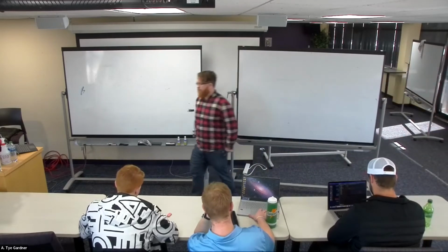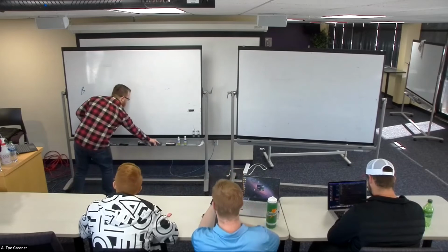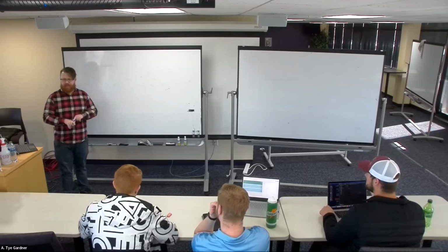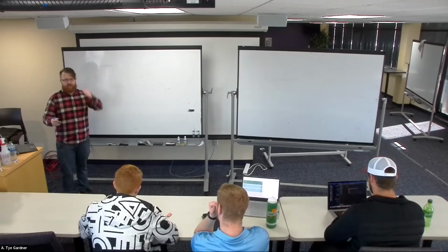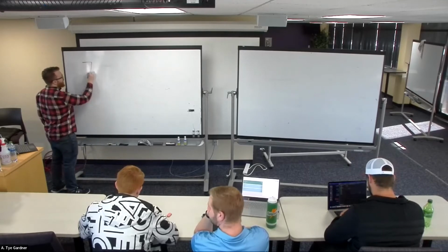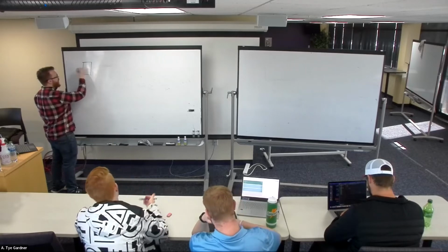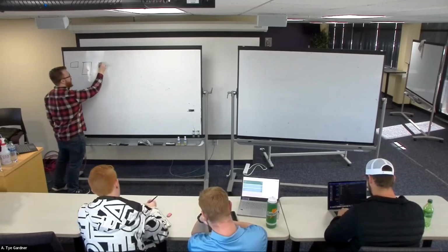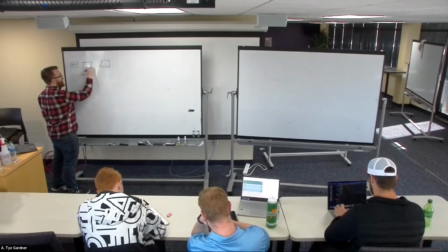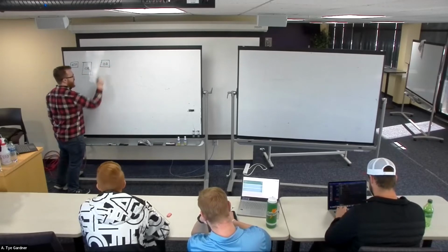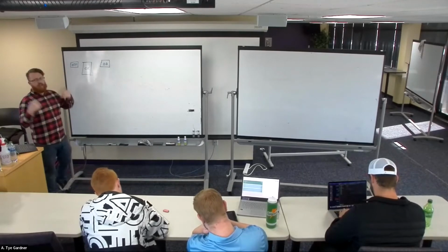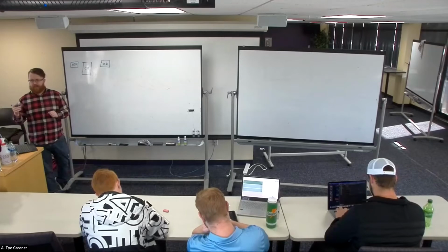So let's talk about state machines in general as the review. If you take my digital circuits course, we'll start off with basically K-maps and then state machines. So you'll get review there again, because it turns out they're really important. So we have 3 parts to any state machine. They're the next state decoder, the current state register, and the output decoder, right? Decoders being we look at some input and we translate it to what our output should be, right?